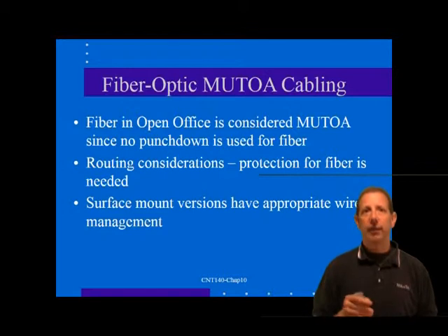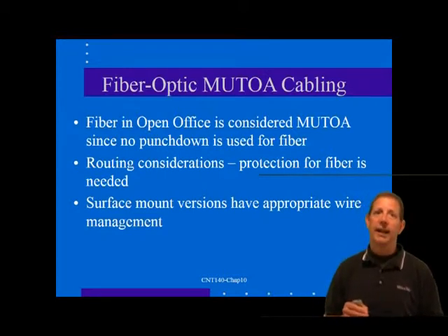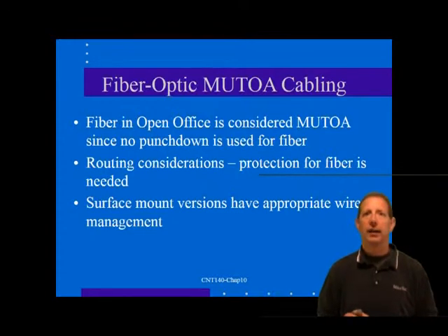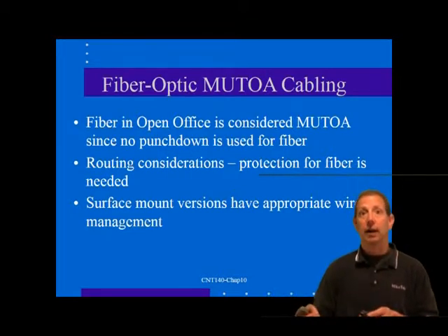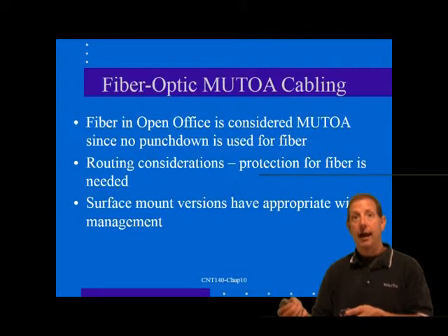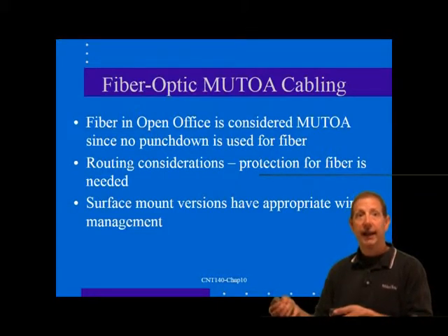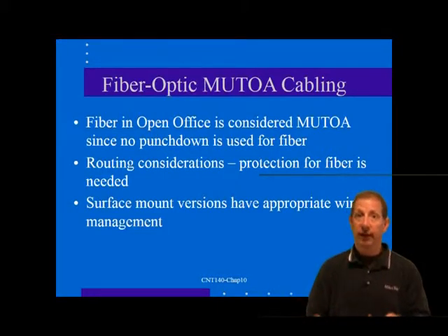Fiber cable strands are generally terminated in a male connector, which is interconnected by aligning the fibers in an adapter receptacle. The terminations and connections at the hub switch in the TR, at the patch panel, at the MUTOA, and at the work area outlets are identical.